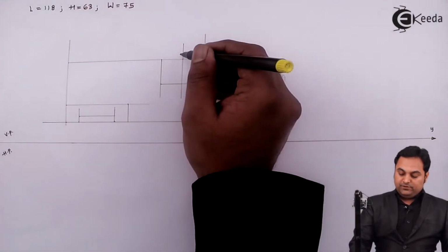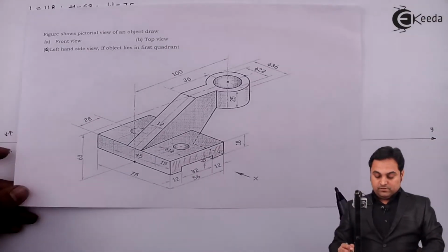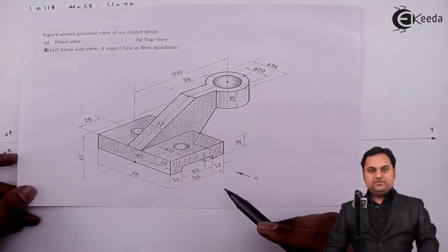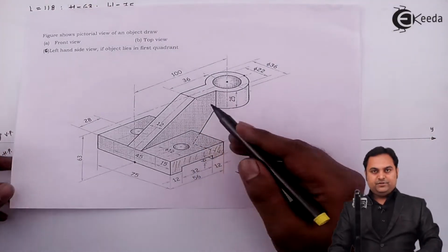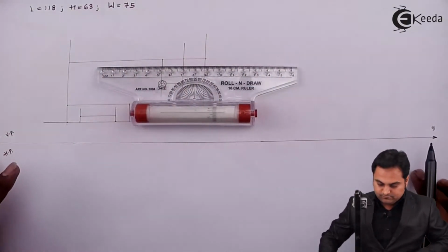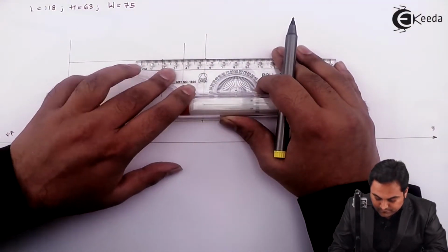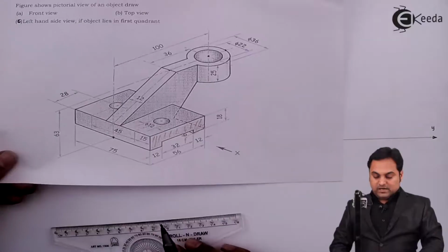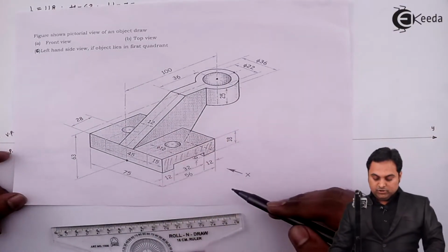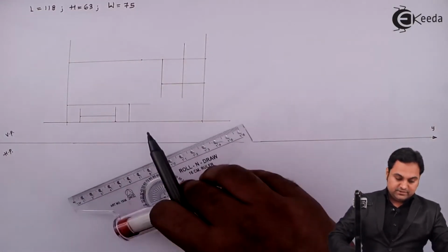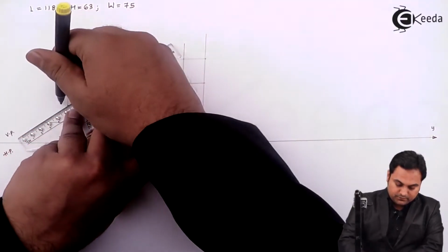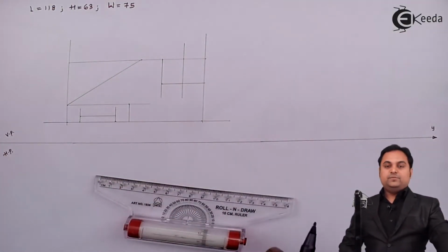Then from here I have to measure 36 mm to get the straight surface, which will be visible from the direction X as a straight horizontal line. So measuring 36 mm. After this straight portion, it is inclined and joining up till here. So from the front, it will look something like this, connected at the extreme end point like this. So this is the portion.